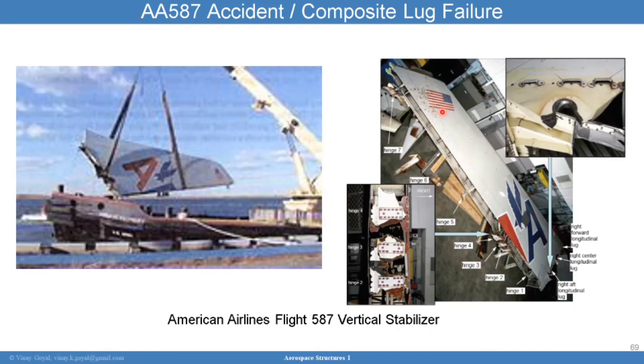And so the force of that air flowing against the moving rudder started to stress the vertical stabilizer. And at some point, the vertical stabilizer snapped off, which then caused the structure to lose stability.